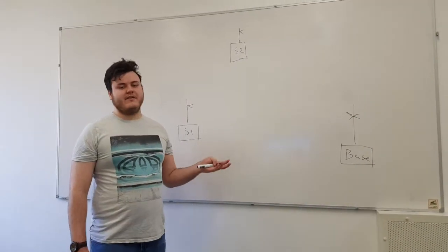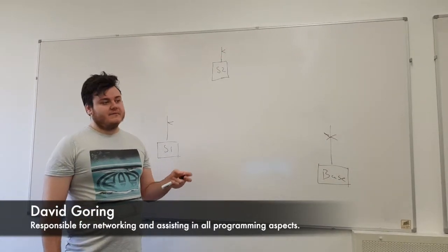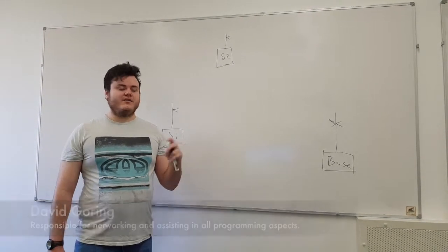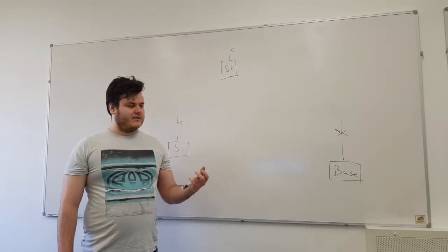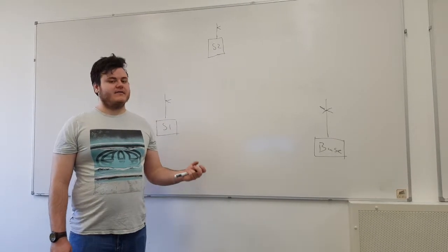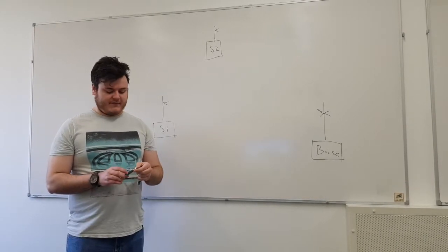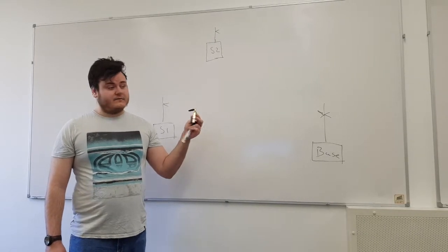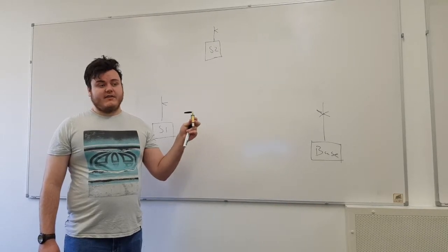So there are a couple of different dongles that we looked at that we could give to the Odroid. Quite a few of them were in the 800 to 900 megahertz range, which would give us a lot greater distance than a 2.4 gigahertz range. But with the amount of data we're sending, we don't really need that high frequency. So we looked even further and we found this, which is a 435 megahertz dongle, which creates a serial port that can attach to the Odroid, and we can use it for that.